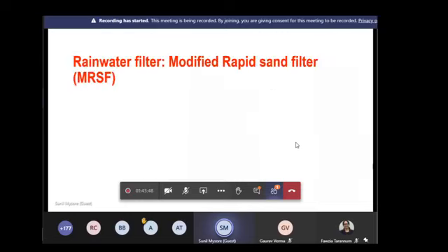Now, the filter, if at all we need to install one, is predominantly 50% for psychological needs, and the other 50% is because generally you still have some amount of dust in spite of the first-flush separation. Particularly in my own house, more than the dust, I have got some soil, I have got a lot of leaves coming in, so I need to trap this. Plus, there is some dissolved gas in the water which I need to absorb. So I use some material like charcoal or activated carbon to take care of that, and some pores in that carbon can actually trap my dust.